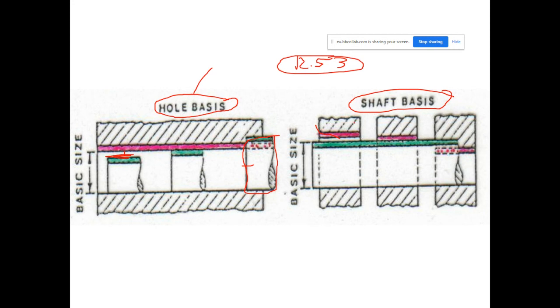Its diameter is equal to that much. Sorry, you cannot find it. What can you do? It is the main reason why shaft basis is not recommended as the technique to set the size of features for having a fitting in the correct order, because in the market, drill cutters are in standard sizes and you cannot find any other to set the size of the feminine feature.